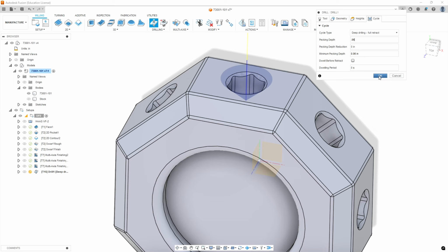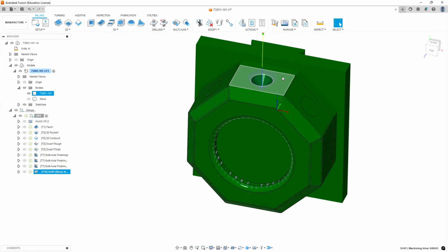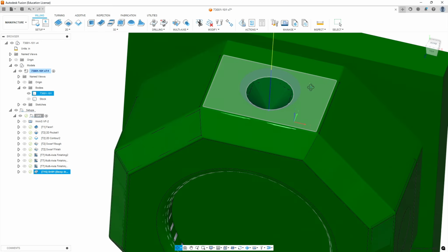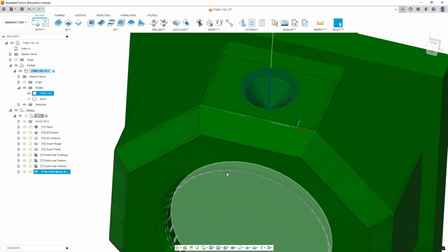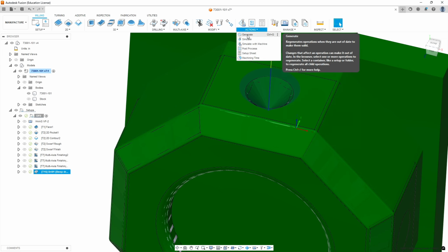And because this is a 2-flute chamfer mill, we're going to actually put a dwell in so it pauses. Make sure that we get a nice chamfer finish. And we're just going to have it dwell 1 second. Okay, and there we go. We've got our first what I would call 3+1 move. It's a 4-axis indexing move.